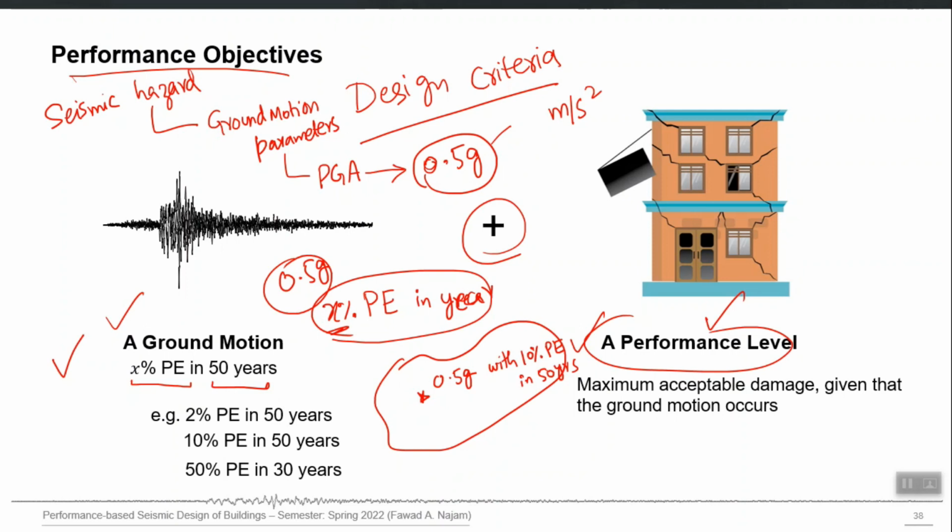Now, if I change it, let us say to 100 years, the number for that same site will be different, right. Actually, this number, 50 years, is the exposure period. It is generally used as the design life of the building. So, we are interested in this number, but generally this 50 years is fixed and we change the probability, right.